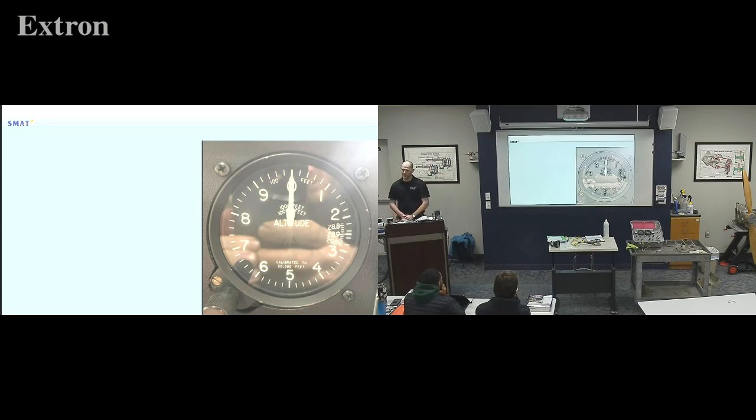Kind of cool, right? Now if I go up to a really high mountain, like say I'm in Denver, I might not be able to do this because the Kollsman window might not have enough range. I might not be able to get it all the way down to 0 because the Kollsman window has to start and stop on each end. So you might not be able to do that if you're farther from sea level. But if you're anywhere near sea level, setting it to 0 will give you the actual pressure around you.